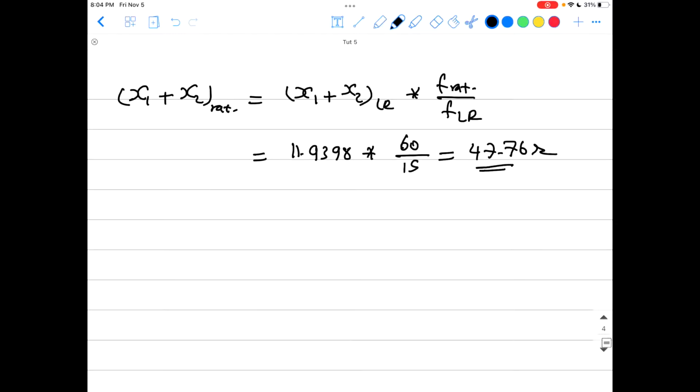How to separate them, like we said, using the table given in the lecture. And as I said, the table said that, if you refer back, if it is a wound rotor machine, then it's 50-50, but it's not wound rotor, it's squirrel cage. So if it is a squirrel cage, you should go with which design code you have. If it is design A, B, C, D, it's different designs for the well-known squirrel cage motor. Like I said in the lecture, if it is not given as in this problem, you just assume it's B design. So assume it is class B. That means X1 equals 40% and X2 equals 60%. Keep that in mind.